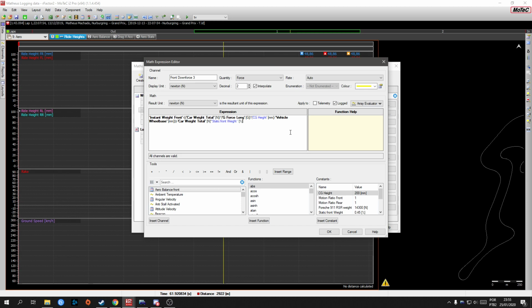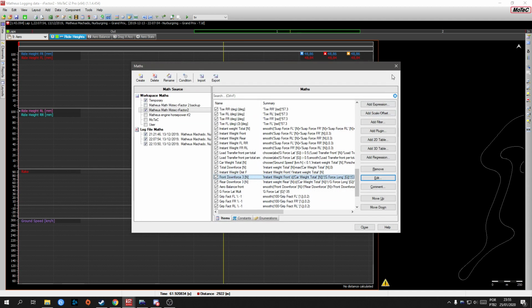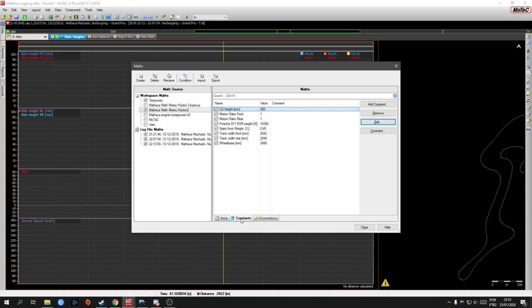and it doesn't make much difference when you go in a straight line, where you can easily compare the downforce values and the drag values and stuff like that. But it does make a difference under braking and accelerating, so you need to take into account that load transfer. So yeah, this is what I use to calculate this. And here, as rFactor 2 already gives you the suspension loads, you don't need the spring rates of the car and the motion ratios of the car to have the exact downforce value.